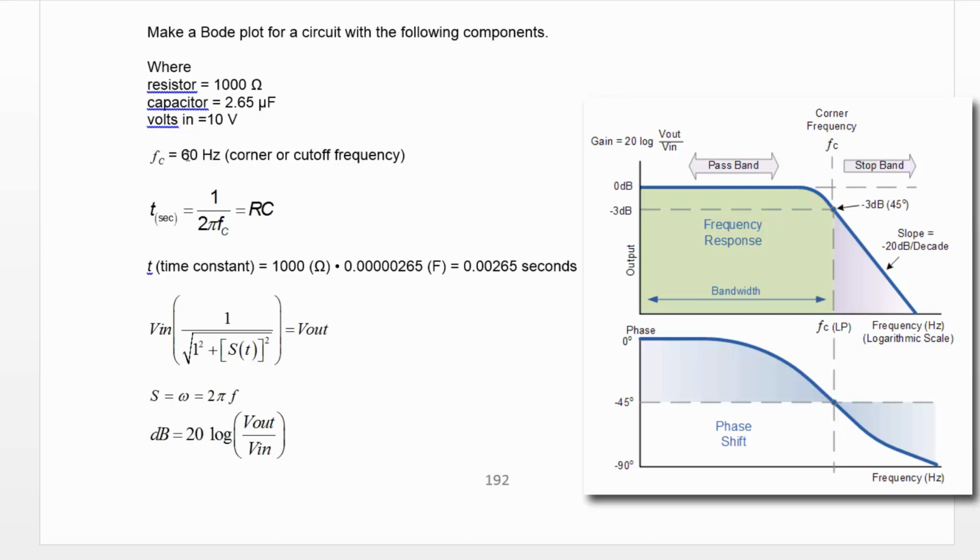And we're doing this as house voltage, 60 hertz. So typically you want 60 hertz. This would be like, say you've got a UPS and it's a 60 hertz UPS, and you've got a 10K messenger signal riding on the voltage to communicate back and forth with electronics, and you want to filter that out.